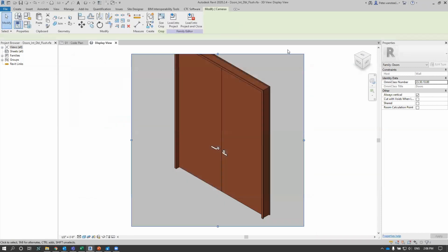Okay. So now we know that we have a good shared parameter file that's actually solid and works with our project. We have all of our loadable content done. We know that the parameters within our families are in fact set up. They're actually working correctly with all of our tags and schedules and everything else. So we know those will work.